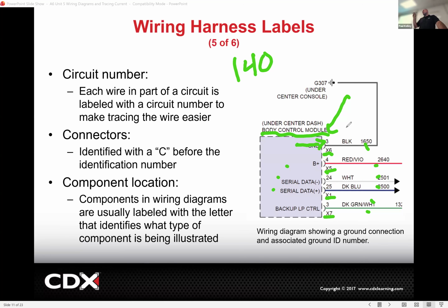Then once you find that out, sometimes it's cool because there'll be different colors. Like maybe 1 is red and 2 is white and 3 is blue. And if we're looking at number 3, then you look for the blue plastic connector. Then you got to look for terminal number 3. So you'd have to look at the connector end view, and it might be like all these wires. Which one is terminal 3? Well, maybe it's right there. And then you double check and make sure it's black. And then be like, okay, yeah, I definitely got the right wire.